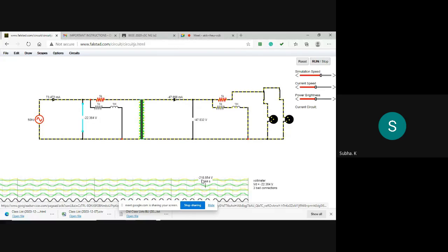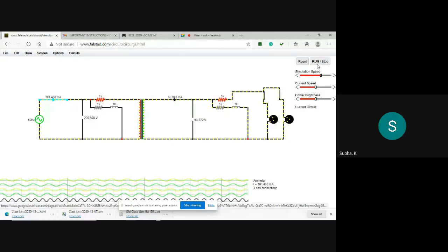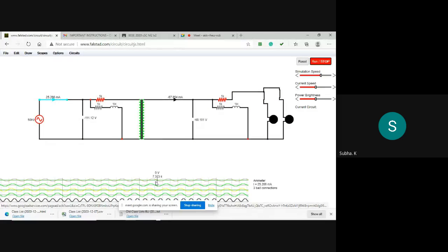For calculating all the parameters, you keep the cursor exactly at the peak. Okay, stop the waveform and keep the cursor exactly at the peak. This is primary voltage, that is around 230 you will get. Around the peak you see, around 230 you have to check. 227 is maximum, means you stop here. This is the primary voltage.